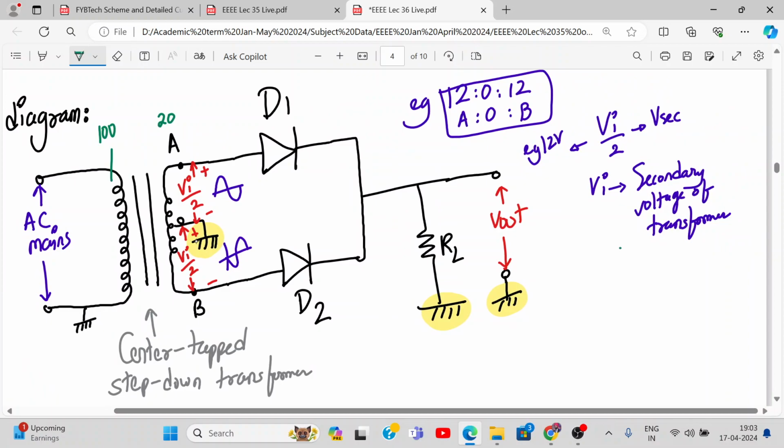Yes. So whenever we have, let's say, phi dash phi, it means this is Vi by 2, Vi by 2. So total voltage Vi will be 10 volt. The 10 volt gets split into 5 and 5. Here we have total 24, but that gets split into 12 to 0, 0 to 12. So that is overall 24. Did you get what I'm saying? So Vi by 2 is 12, so Vi will be 24. Your Vi by 2 is 5, so Vi will be 10. Understood this? Yes or no? Tell me. Because this is the tricky part.